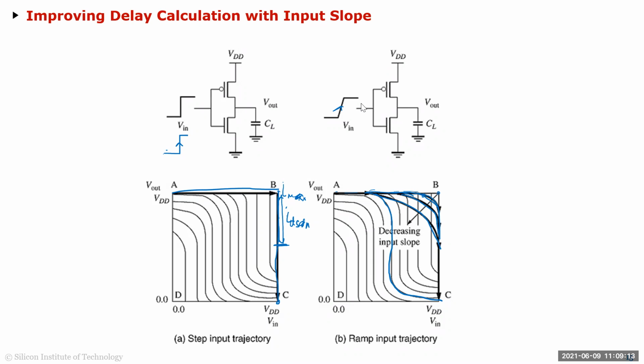Yeah, but just like I said, understand the principle of what we are doing. We're trying to basically model the delays, because that's essentially what you're going to do in digital design. If you're a back-end designer, like in STA, static timing analysis, all you're doing is delay analysis all the time. So that's why you need to have a clear understanding of where the delays are coming from, right? Essentially they're coming from the resistance of your switches, your load capacitances, and the delay of your input rise times. These are the three things we have discussed.